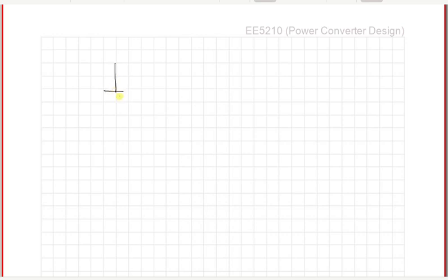like this. It had an input voltage source Vg, and then you had a switch which would connect this to some terminal where you will get the pulsating DC voltage, and then you connected an LC filter to filter this DC voltage, okay.